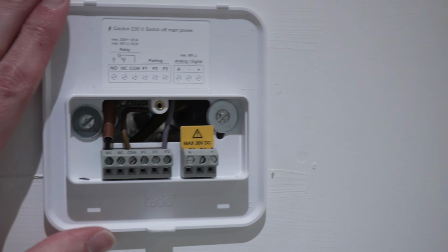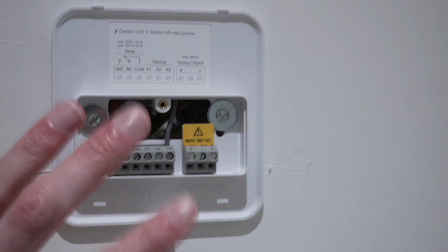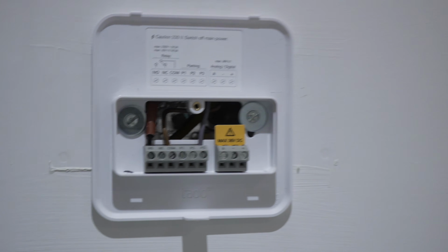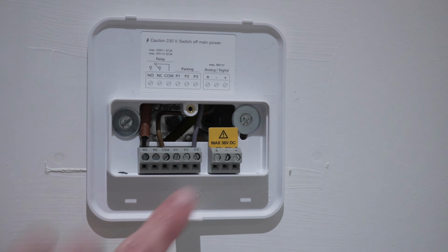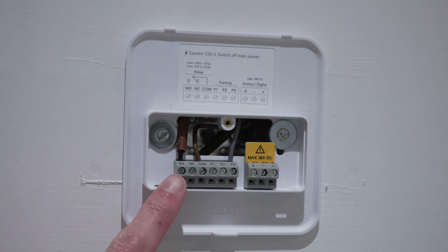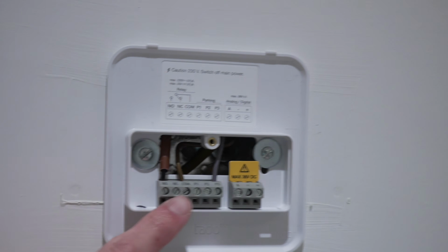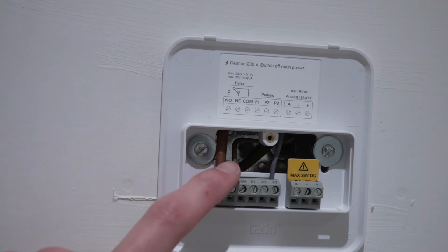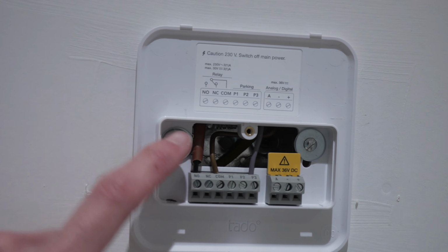Of course, this has already been safely isolated and properly tested before I took the front off and started touching this. Do not start messing about with this until you've properly isolated the power to your heating system and tested it as well to make sure it is isolated. But what we can see here is the terminals. So what we have is our permanent line here and then our switch line here. So the brown is a permanent line that comes in,